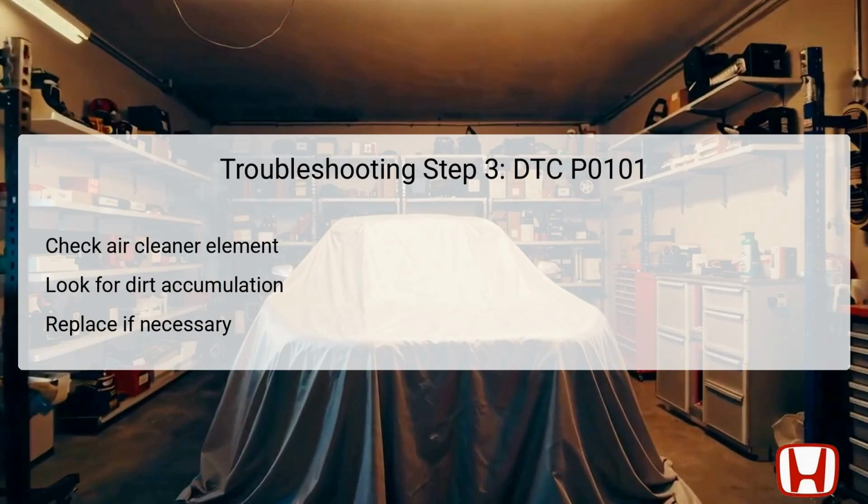If the air cleaner is found to be excessively dirty or clogged, replacement is necessary to restore optimal intake air levels. Conversely, if inspection shows that the air cleaner is clean and acceptable, the troubleshooting steps can continue accordingly. It is important to note that maintaining a clean air cleaner element is crucial, as it not only affects MAF performance, but also engine longevity.